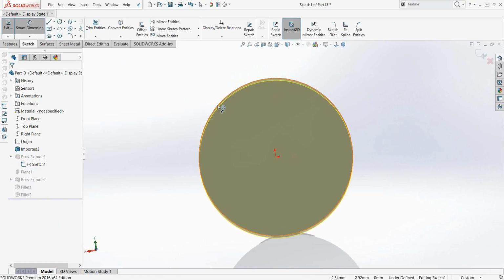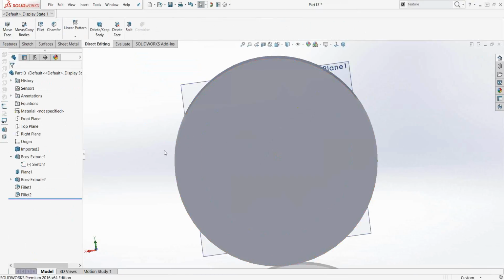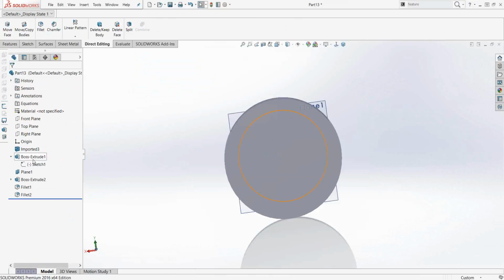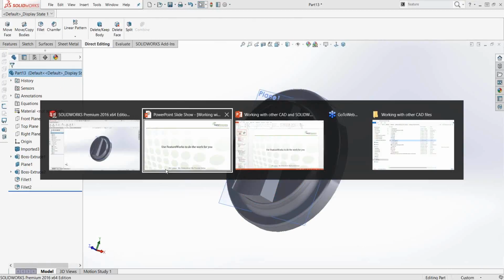and you can just throw some dimensions on there, or just do fully define sketch, then check out of it to get those sketches defined. So you may just want to do that before you go ahead and start editing things further down in the tree, to avoid confusion or to avoid your model from collapsing on itself. So just be aware of that. Let's jump back into the PowerPoint.